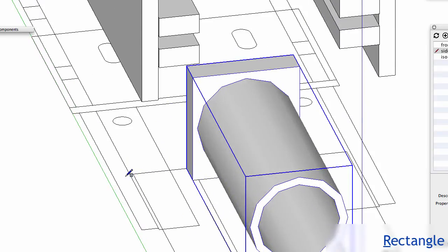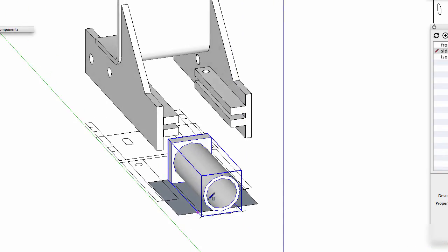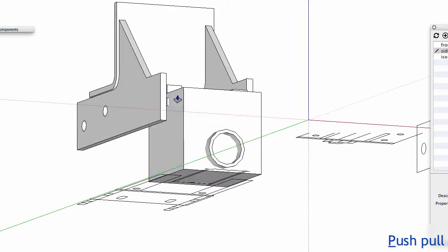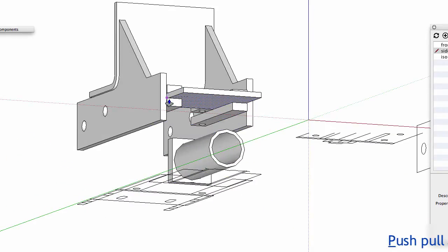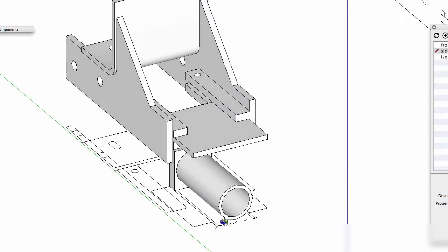See, there's a little bit of a gap between the plate and this new plate. So we use the CAD line work for the plate. P to push-pull it. Touch the bottom corner of that plate, orbit underneath, click, push-pull it up, find the top corner. So there's the thickness of that metal plate.